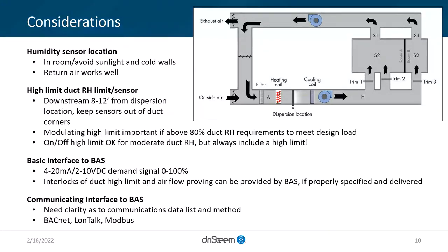And also, if you're doing an in-space type application where your humidifier is putting that moisture into the space, you don't want to spray, whether that's liquid droplets from high pressure atomization or even isothermal steam, where that sensor may be directly in front of a nozzle or directly in front of an SDU. That would give some false positive readings that we want to eliminate.